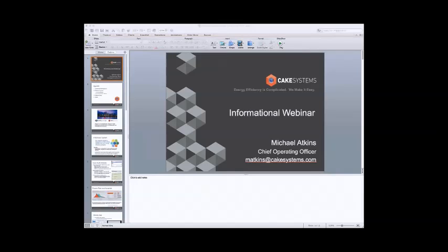It was originally done in order to simplify the homeowner's view of how much energy the home is using. We are customizing our user interface for the California platform to show you, the auditor, both therms and kilowatts separately, because we know you need that for your incentive calculation. But in the report, like I said, originally the intent was to simplify talking to homeowners about energy. So everything has been converted over into a kilowatt-hour equivalent by converting the BTUs into kilowatt hours.